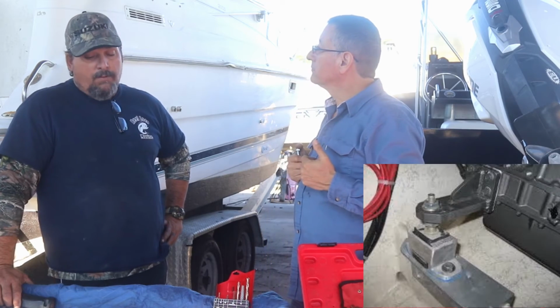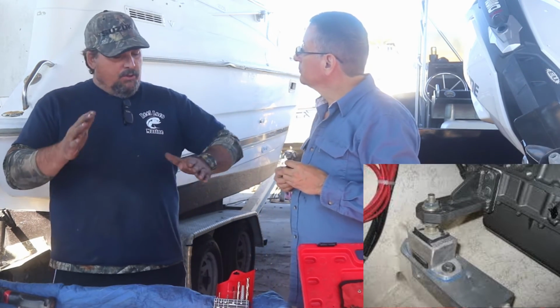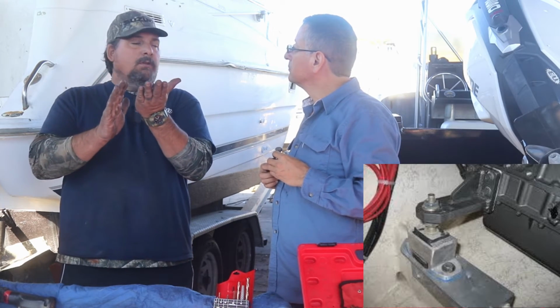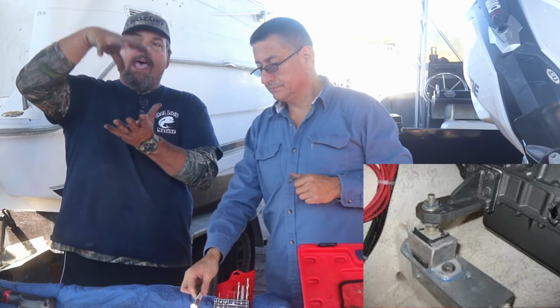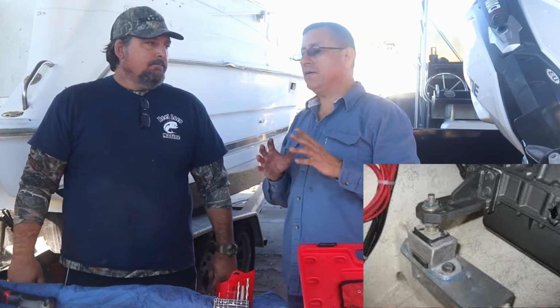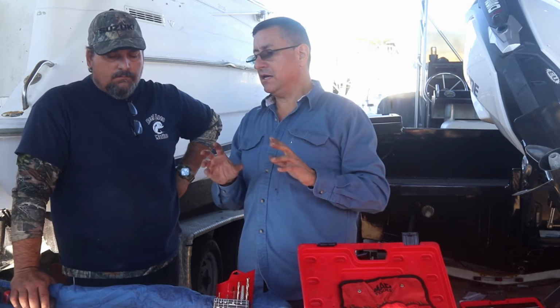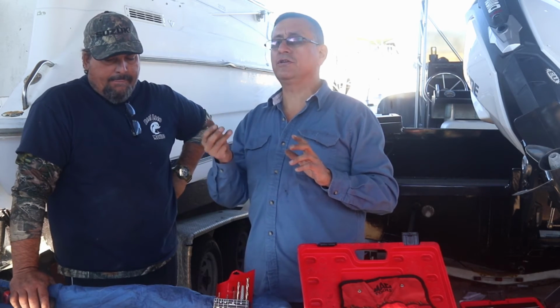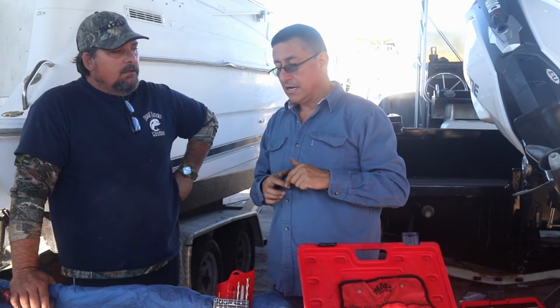Right. Yeah, because some motor mounts, depending on the application, they'll put aluminum 90-degree angle, either stainless or heavy-duty aluminum. Correct. And then they'll mount that on there, and it'll be lagged in or through-bolted through the stringer. Correct. And my friends, be careful with the material. We have different types of applications and different types of alloys used in this marine business.